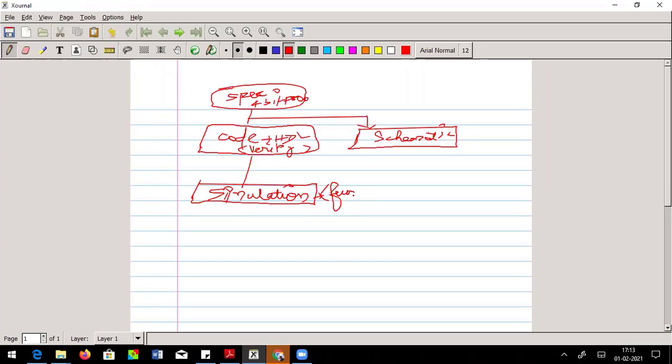That is, say, I have made a 4-bit adder. So what I'm trying to do, I just assign A to be some 4-bit, B to be some 4-bit, and I see whether the sum and carry is same for all possible combinations of my input. So a simulation is a mere process of verifying the code which you have written, such that if the test inputs are given, whether it is giving the functional output required by the system.